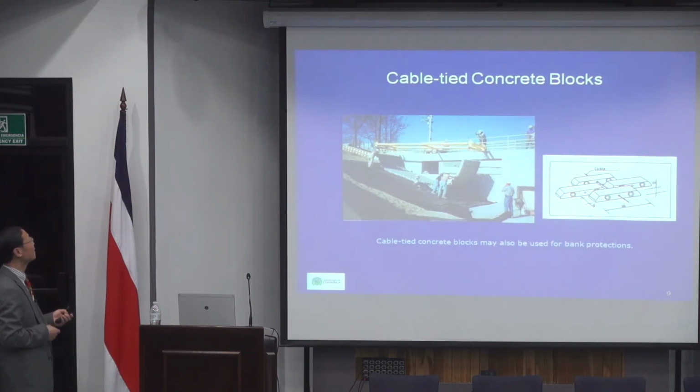Another thing we use a lot: you can use riprap, but you can also use prefabricated concrete blocks with cable ties. These are flexible, so you just erect these and they can lay down, and that provides very good protection as well.